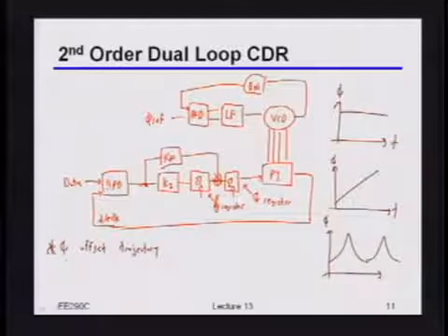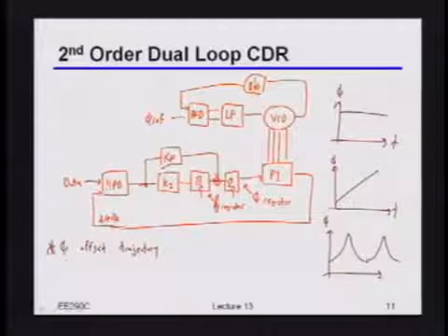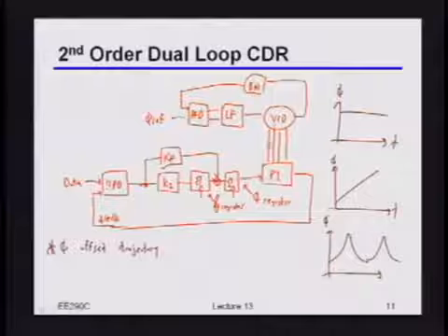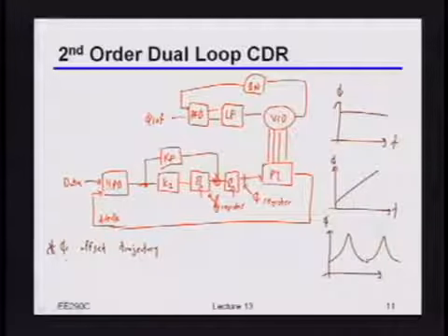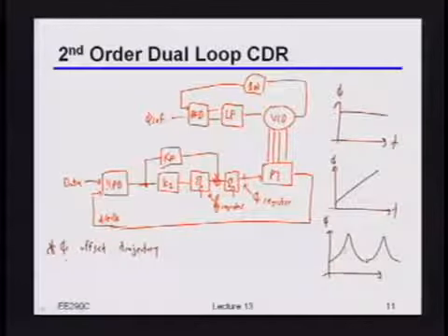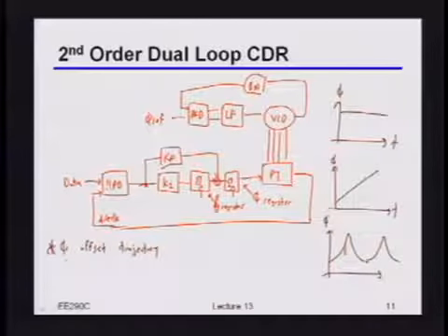Okay, there are lots of different ways you can do it. Among the choices of techniques are adjusting the divide ratio dynamically, and in fact usually using some fractional-N PLL for that. There are similar examples we'll walk through in a second, where let's say you had a phase interpolator at your output, and then instead of tying it into a feedback loop, you had some deterministic trajectory you created through that phase interpolator. Basically, pretty much anything that mucks around with the PLL, you can use to create really weird looking trajectories, especially if you know what you want to do. Not to say that it's an easy thing to do, but there are lots of different ways that can potentially be done. Okay?